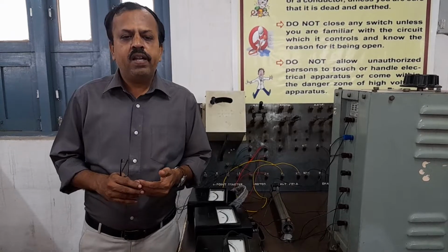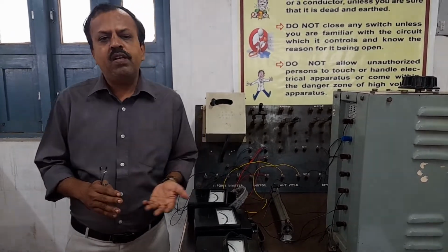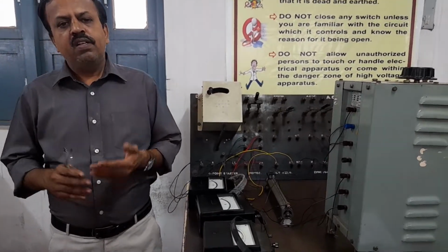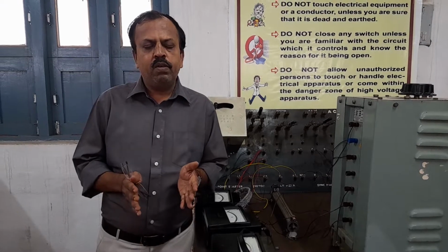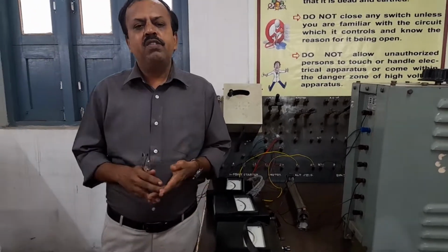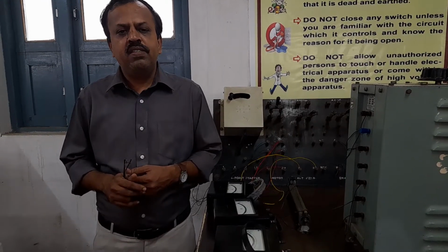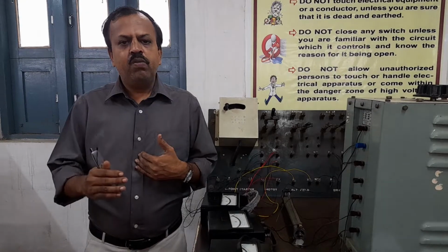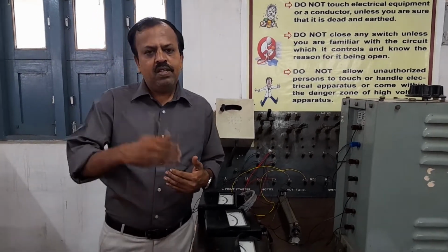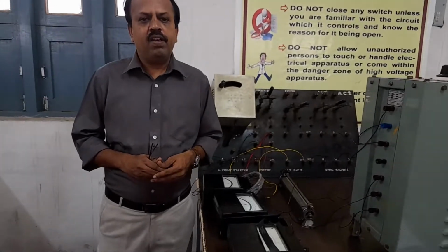So we will be getting one reactance along the field pole axis which is maximum, and we call it as direct axis reactance. In a similar way, the reactance in between the axis of the field poles will be very large, and we take that reactance as XQ, that is quadrature axis reactance. So how do you determine this XD and XQ experimentally? We will see that right now by conducting a slip test on alternator.